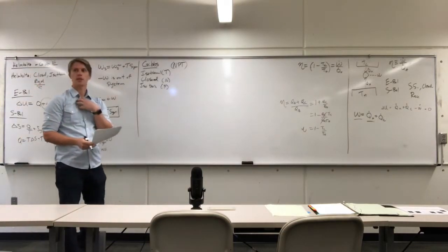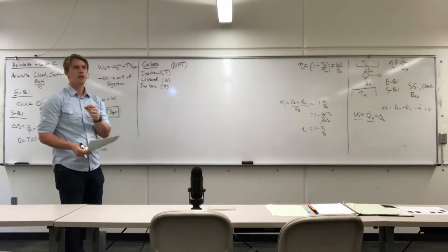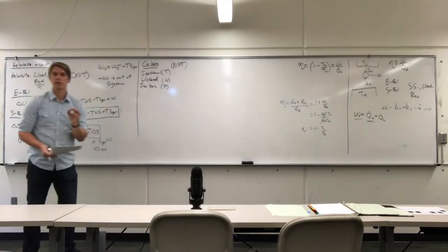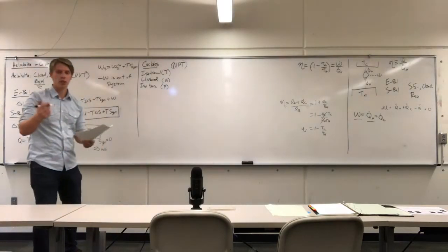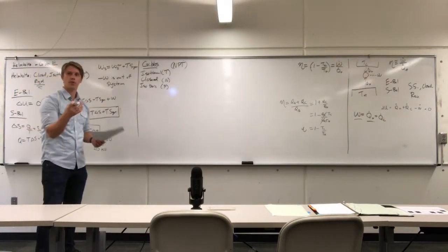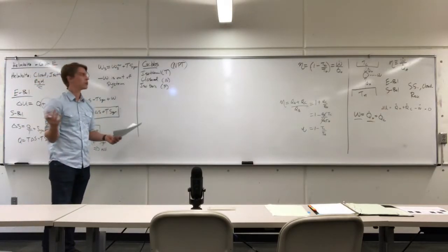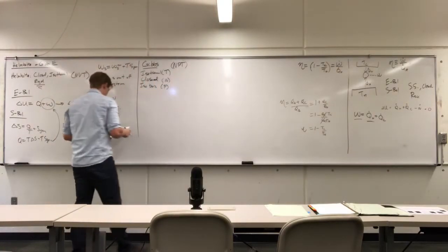And for our purposes as chemical engineers, most generally NPT is the most convenient because they're the easiest functions to measure, temperature and pressure, right? Because we don't have an internal energy gauge that we can just slap on the side of a tank. We can very trivially, with a thermocouple or a pressure gauge, measure temperature and pressure. So for controls purposes, that's why we like controlling pressure and temperature.